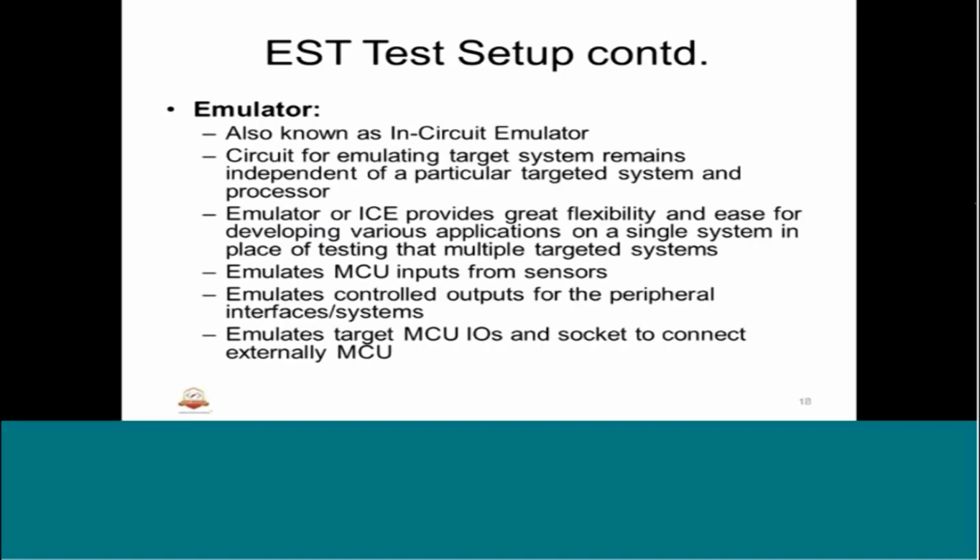So what is an emulator? It is also called an in-circuit emulator. It takes the in-circuit values and provides the user a gist of the values that are going on with the target, so it emulates what is needed. Similarly, the user can put values into the registers with the help of emulators. The emulator is also known as the in-circuit emulator, ICE. The circuit for emulating the target system remains independent of a particular target system and processor.